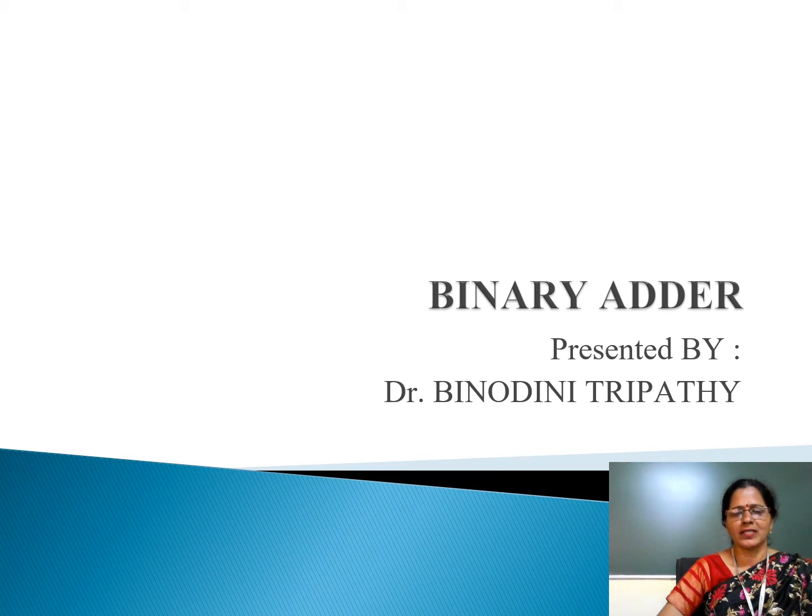So, as per the before class, we have already discussed the combinational circuits. As per the before class, a combinational circuit is a circuit which has no memory capacity, no feedback, and the present output depends upon the present input. That type of circuit is basically known as a combinational circuit. We have also discussed different examples of combinational circuits, and the most important examples are the adder, subtractor, multiplexer, demultiplexer, encoder, decoder, and so on.